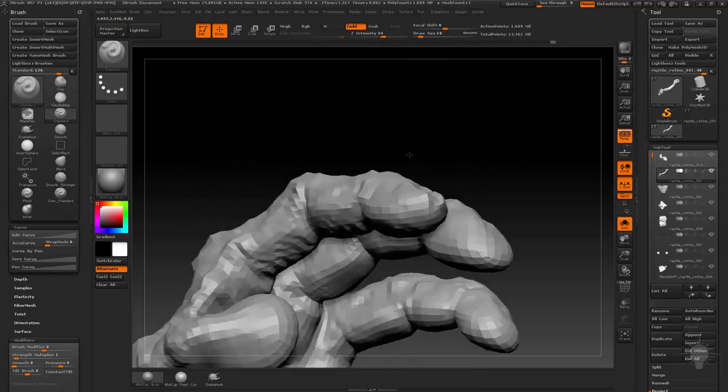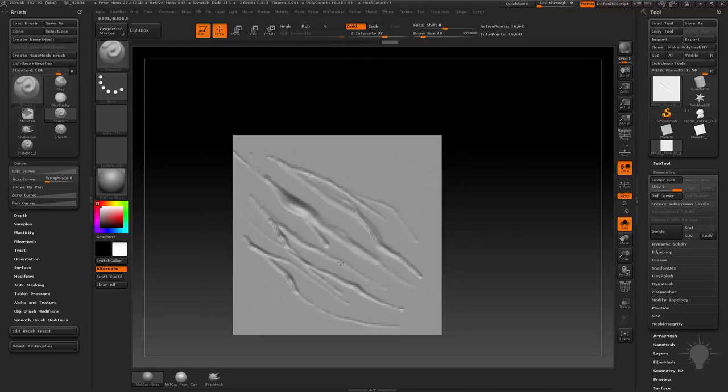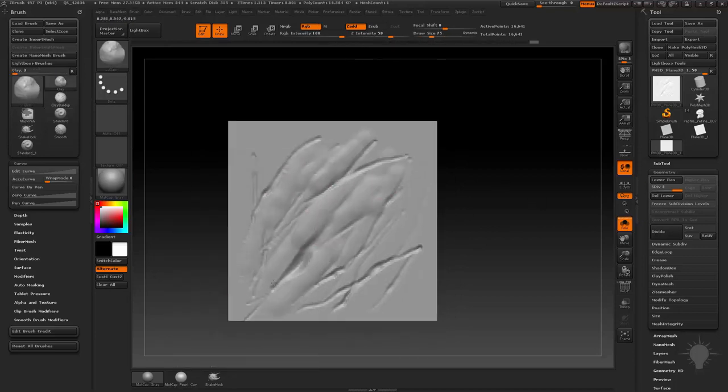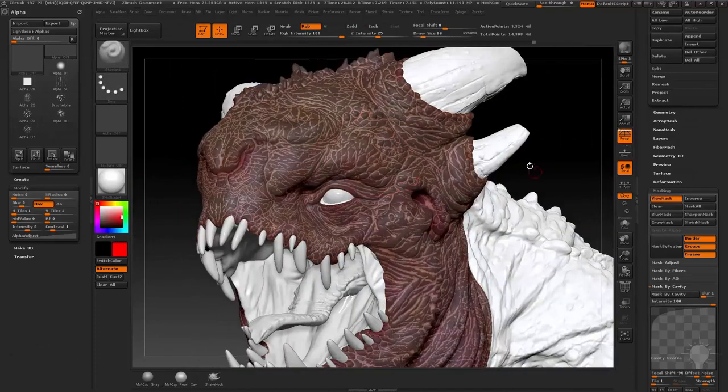We'll also talk about skin direction and different techniques to achieve the surface look you're going for, using alphas for detail, as well as creating your own alphas from scratch right within ZBrush. We'll cover surface noise, curved brushes, and finally you'll get to poly painting.